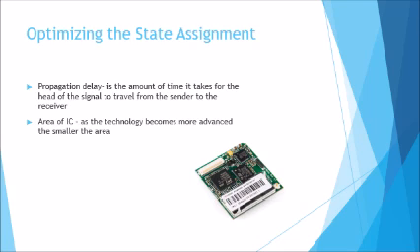In electronics, digital circuits, and digital electronics, the propagation delay, also known as the gate delay, is the length of time which starts when the input to a logic gate becomes stable and valid to change to the time that the output of the logic gate is stable and valid to change. Second is the area of integrated circuits, and as the technology for the circuits becomes more advanced, the smaller the area is going to become.